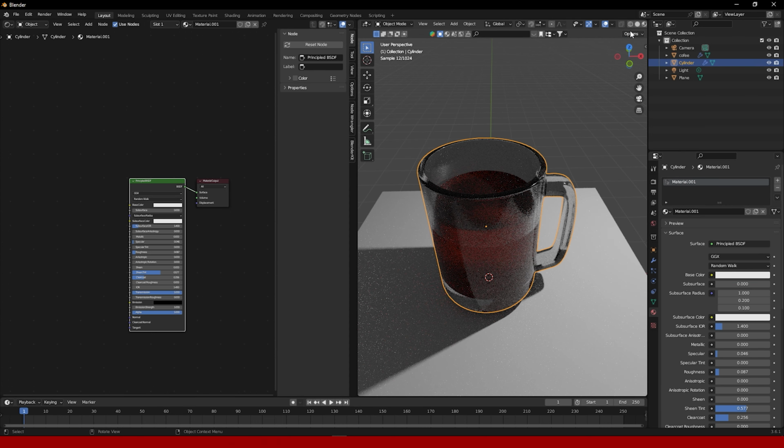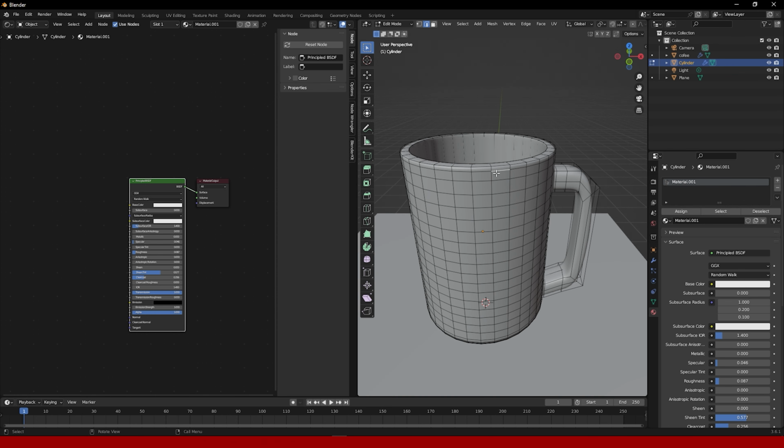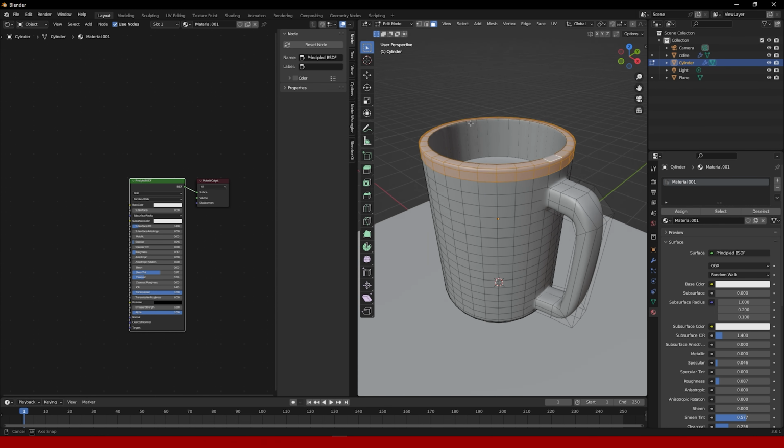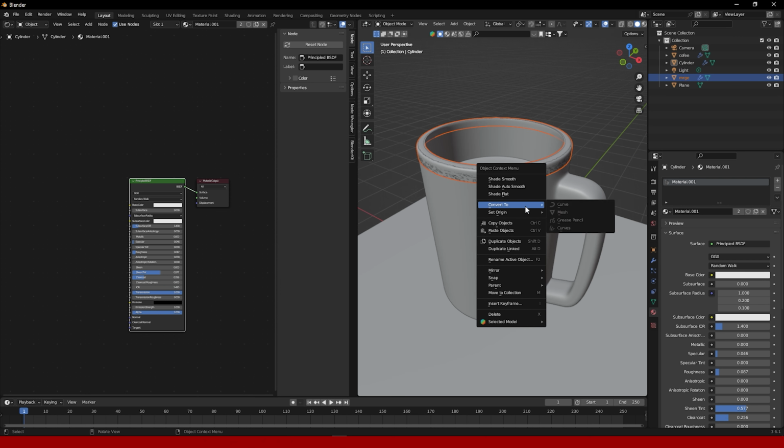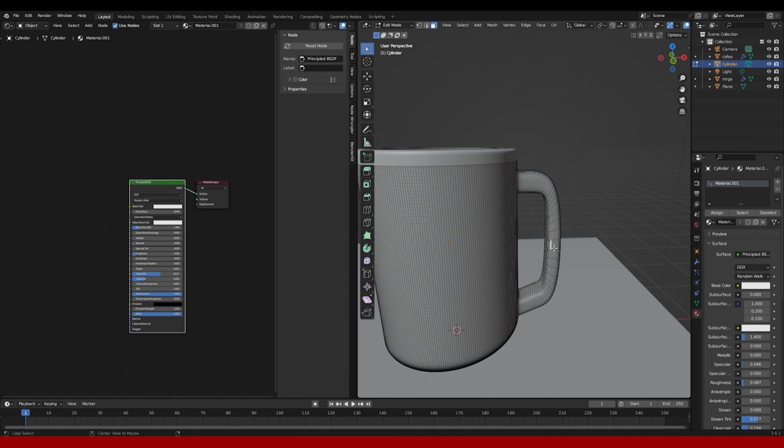And I'm going to add wood parts to this mug, but I didn't have this idea before, so I selected top faces of this mug and I separated this selected mesh, and I right click, I go to set origin to geometry, and basically this option moves the origin to the center of the object. Now I'm gonna add wood parts to our mug handle.